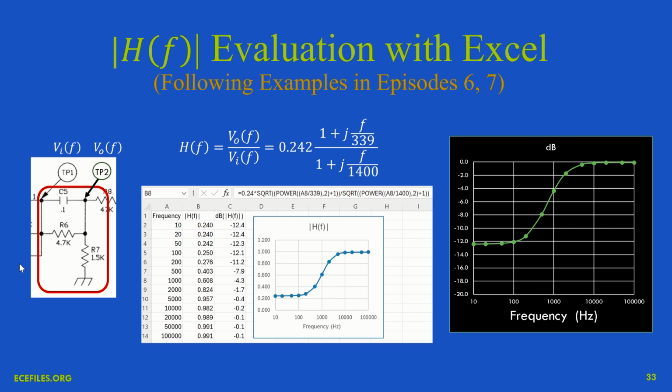So that's no doubt what went into the design of this circuit and the selection of the particular R and C values, giving us a response that looks like this. 165 hertz is about here, about negative 12 dB. And then the higher harmonics are out here. So relative to the fundamental, they'll be 12 dB higher now.